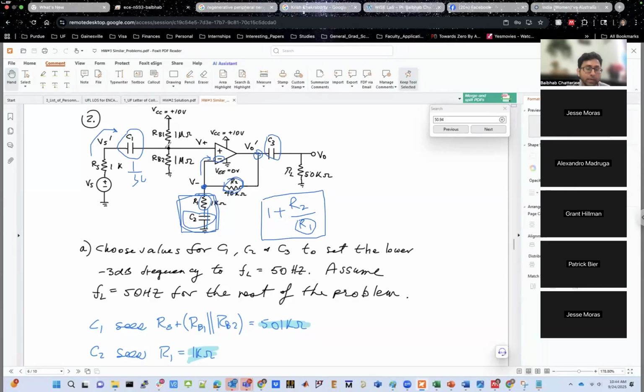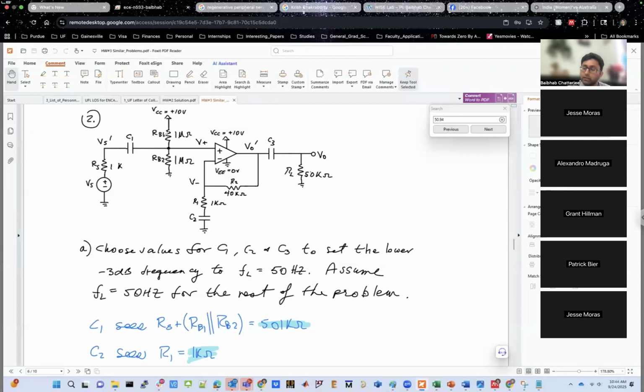Of course, at the input side at the V plus terminal, the input DC bias is fixed by these RB1 and RB2 resistors. Right? So that's something we already discussed in the previous lecture. One other thing that we discussed was what are the poles that need to be considered for this circuit? And of course, as you know, this C1 in series with some kind of a resistive network connected to ground after that forms a high pass filter.